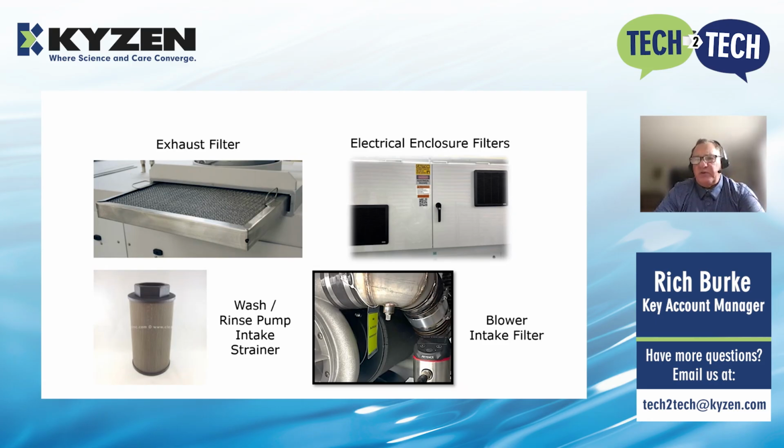So, if those filters become clogged, it limits the ability for the heat to be dissipated from the electrical enclosure, and that can impact the performance and or longevity of our electrical components. And then, of course, we have intake strainers on our wash rinse pumps, blowers.